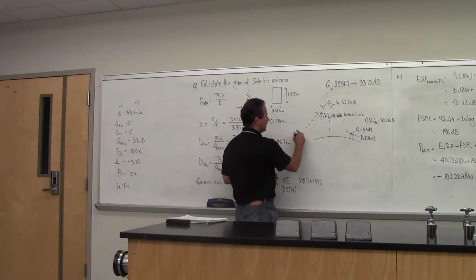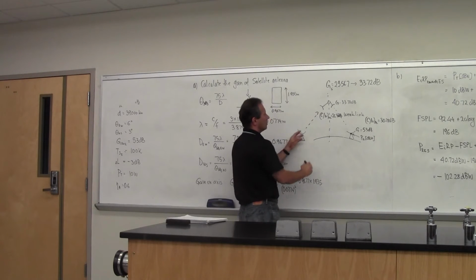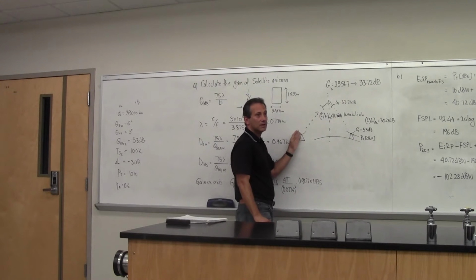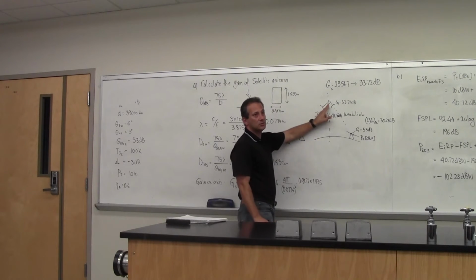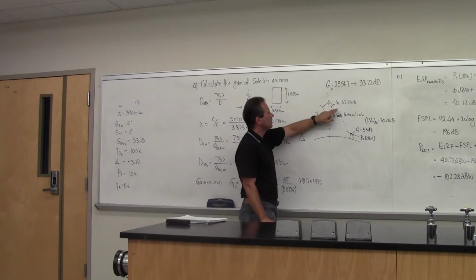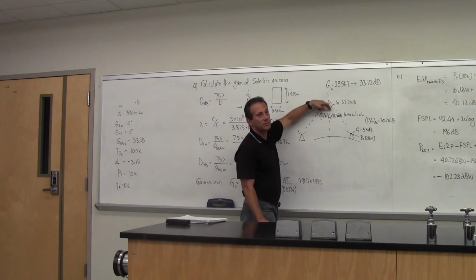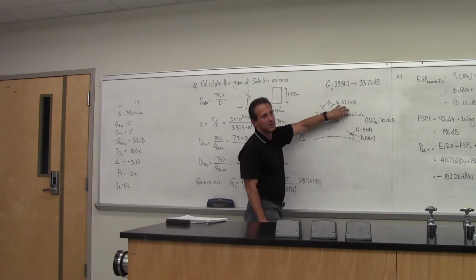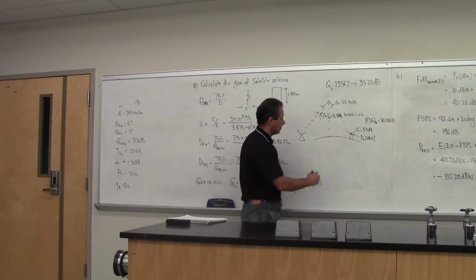Theoretically and practically, you can say, oh, okay, this is 26. Let me increase the power here. You just get a more powerful antenna, or a bigger antenna, or a more powerful amplifier, and you bring this C to N to whatever it needs to be. Here, it is much more cost prohibitive to do that. So really, most of the time, this link is limited.